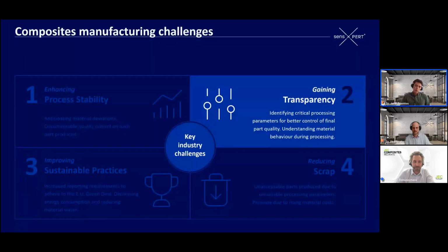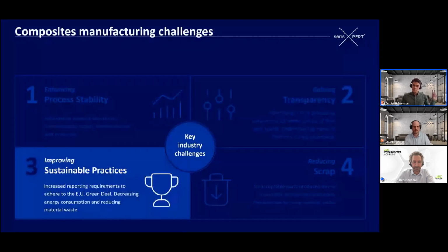So within this black box, what we hope to do is to give you an open window, a really wide window, but we are trying to give you the critical parameters that can help you in the manufacturing process, and what is really happening with the composite. In most cases, we are working with a thermosetting composite, so we will have these chemical and physical transitions, from liquid, gelation, solid.